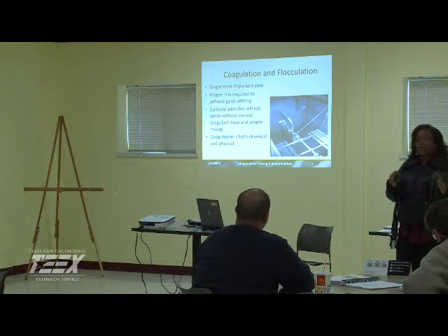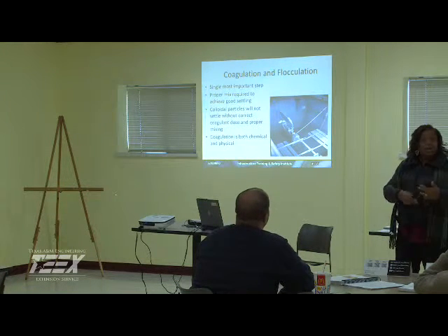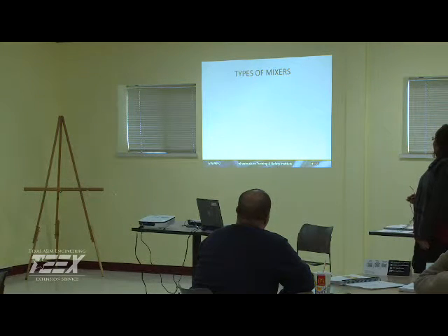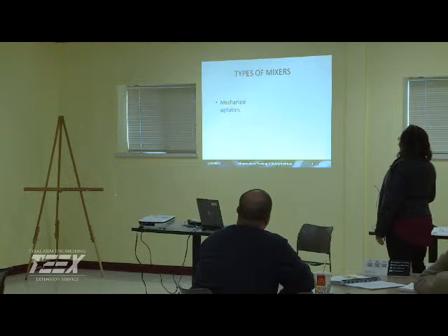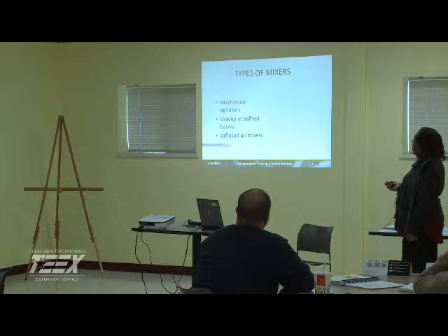And when you're setting up your jar test, try to simulate whatever is going on at your plant as far as the speed and all. There are different types of mixers out there: mechanical agitators, gravity in baffle basins, as well as diffused air mixers, static inline mixers.